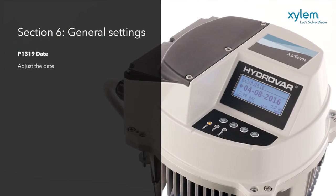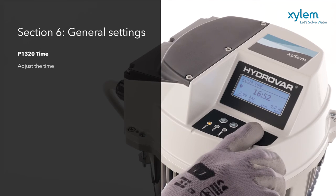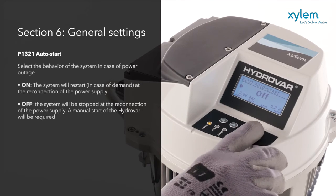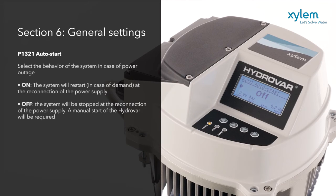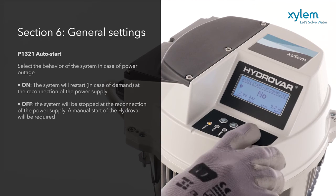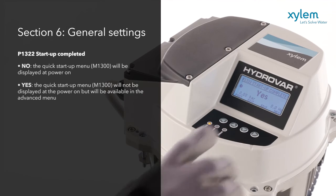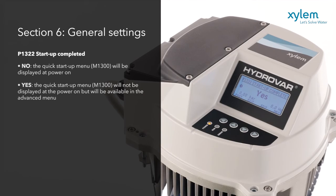The date and time on the embedded time clock can then be set. The Auto Start feature will set Hydrovar to start automatically after a power outage to suit system conditions or demand. If Auto Start is disabled, the unit remains inactive. The control panel will now ask if setup is complete. Select Yes to store the settings for operation. Select No, and the startup procedure is shown again at the next power-up.